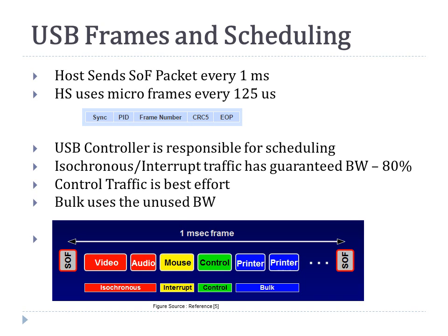And the isochronous and the interrupt transfers by themselves share about 80% of the frame bandwidth, and the remaining bandwidth is assigned to the control transfers, and if anything is available, it is assigned to the bulk transfers, which are not time sensitive, like sending a large amount of data to the printer for printing, or to the hard drive for backup.